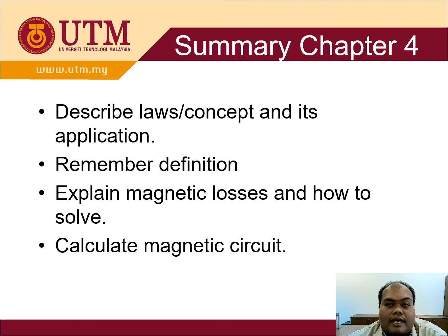Maybe sometimes it gives the same material but different dimensions, so you have to know that each dimension has different reluctance. There is also a question with different materials, so you have to consider two different mu r, relative permeability.